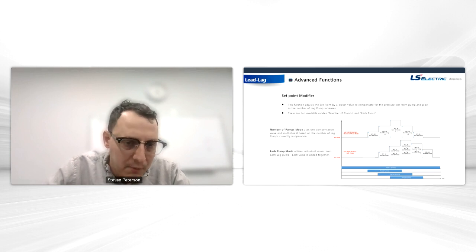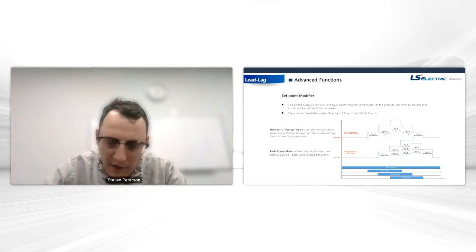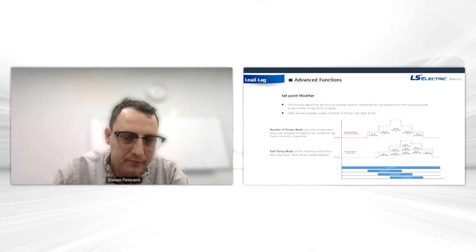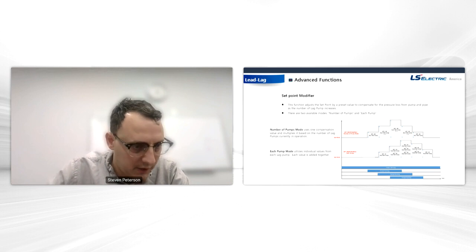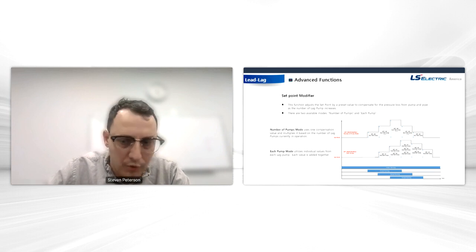And then this each pump one utilizes individual values, so a value for each lag pump, and it adds them together. So you're not multiplying by the same value every time, it's adding based on whatever you pre-program. So there's add this value, add this and this, add this and this and this, and then same thing when it's destaging. Subtract this, subtract this, subtract this. So we have had some requests, for certain applications, to program this. So that is now a standard feature.